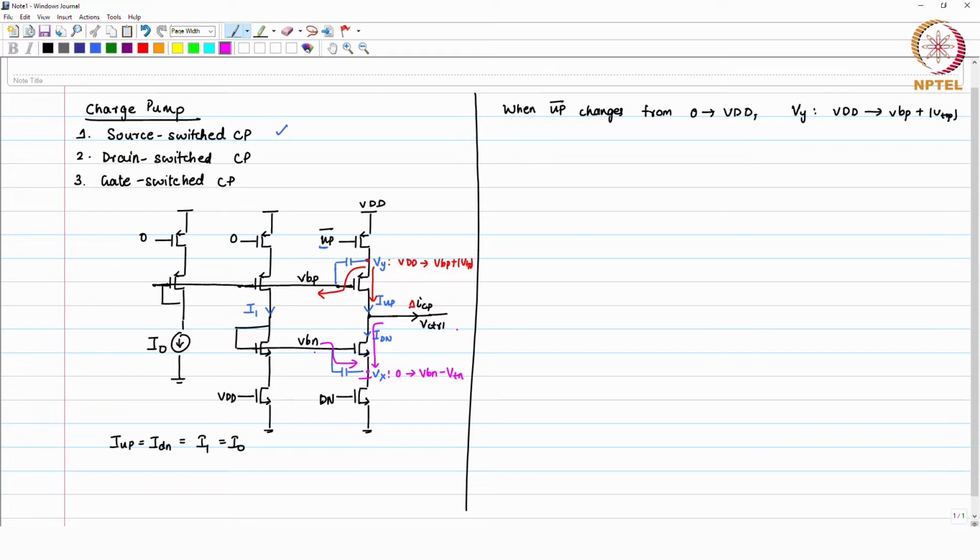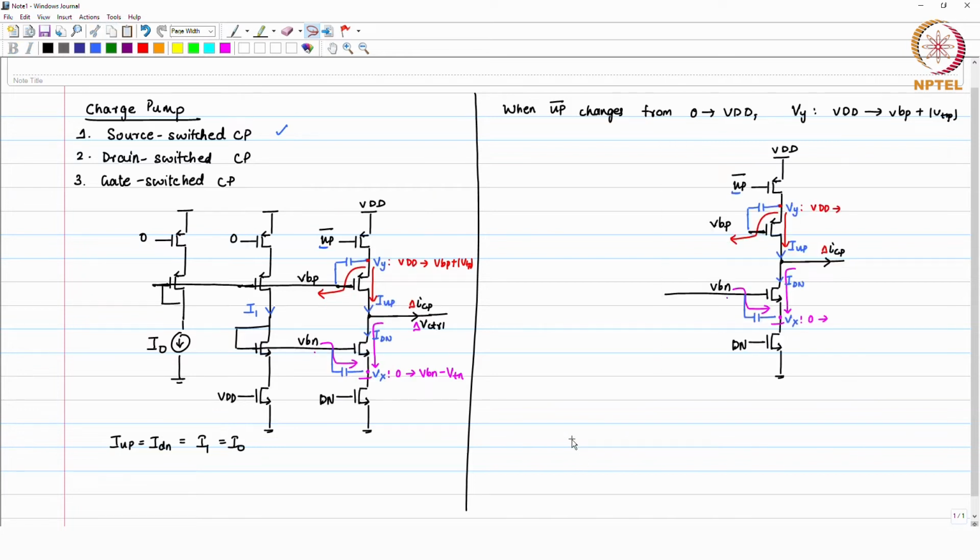This is unwanted current which you have. If you do not minimize it, it will create disturbance in the control voltage, and we have seen at least at system level that if you have a change in the control voltage, this is going to modulate the frequency of the VCO, and thereby it is going to add to the reference spur. So, what we can do is the following. In place of leaving this circuit as such, what we can do is, let me just redraw this.